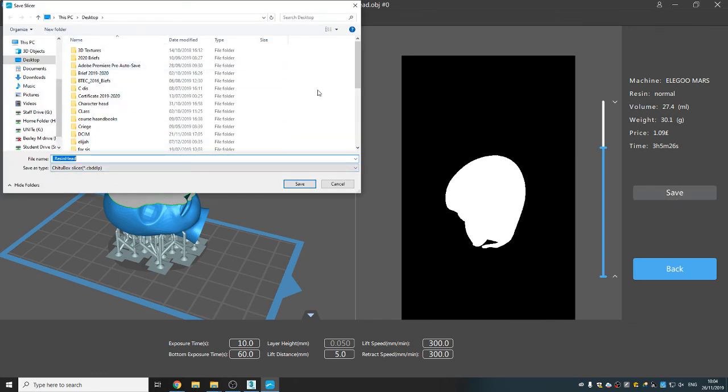And what we want to do is use a memory stick, which we will only use for this, to plug into our 3D printer. We'll put the file into a folder where the printer can locate it, in a format the printer can understand, and then we select it on the user screen there. So I'm just going to plug in this USB that I have in my pocket.